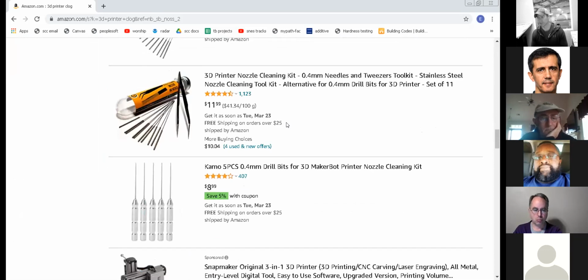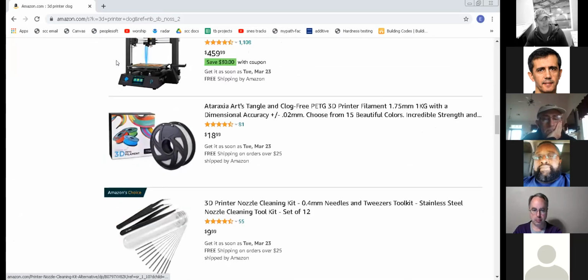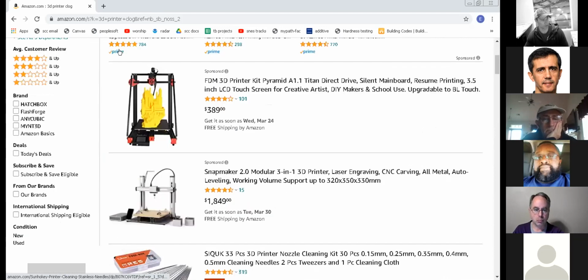Okay. One of the things to keep handy with the resins is always keep your gloves, and keep your little tank of isopropyl alcohol around for the cleaning process. You can set the parts in the window for faster curing, or you can build a little UV box. Check this out. This will speed up your curing.